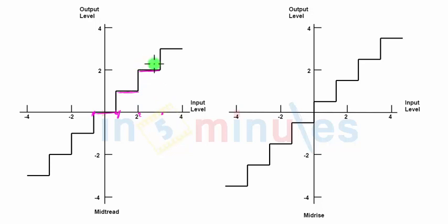Similarly, on the negative side also, when the signal falls between these 2 points and this previously defined point, any input signal which falls between these 2 points will be assigned the fixed level represented by this much value. This will obviously correspond to some negative voltage level. Likewise, every input signal value, which is the sampled value, will be assigned some fixed levels, and you can see the levels we have marked using these horizontal lines.